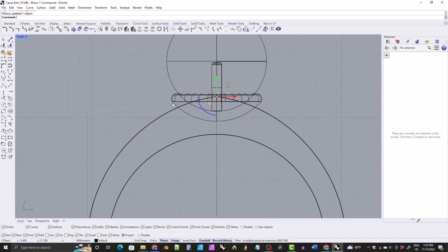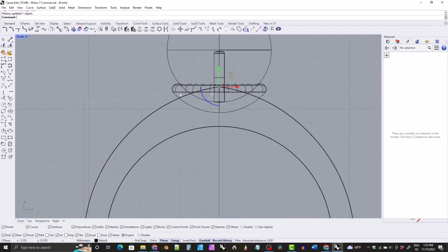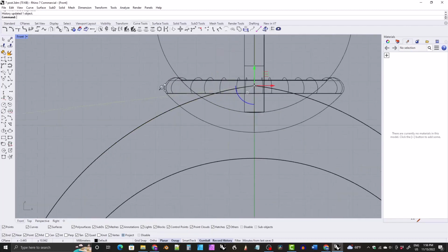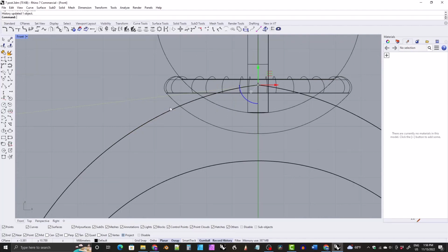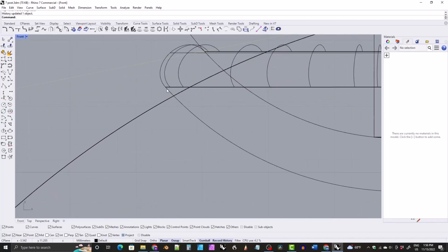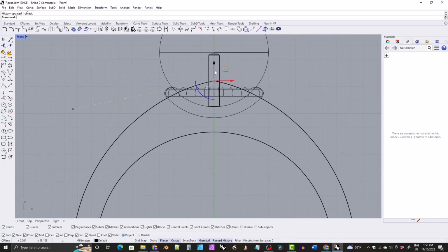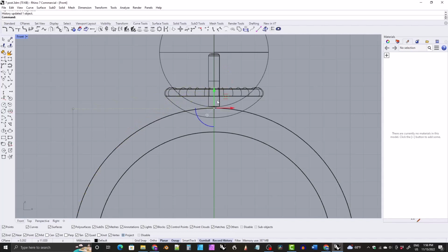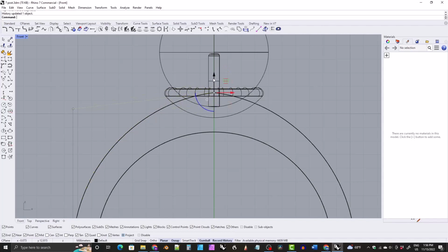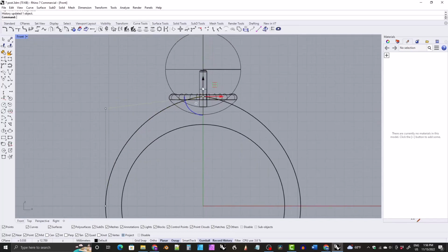And I'm really thinking about the distance between this line and the edge of the cup as well. Because I know I want to put a fairly large, like a 0.3 millimeter fillet here. So you don't want it to be like this, or the fillet would have to come after this edge. So you'd have to come down at least 0.3 millimeters for there to be a 0.3 millimeter fillet there. So this is too high, and this is probably too low. So somewhere in between those two extremes, and I would probably just eyeball it typically.